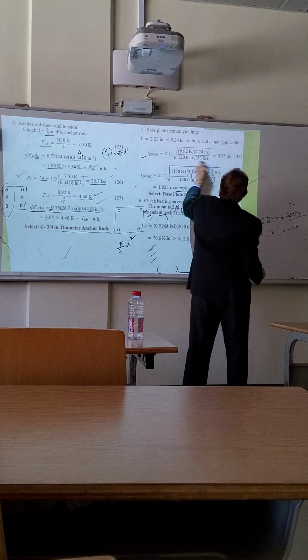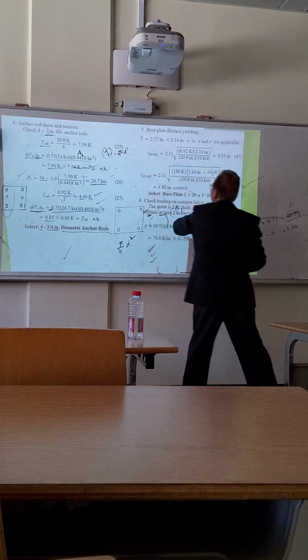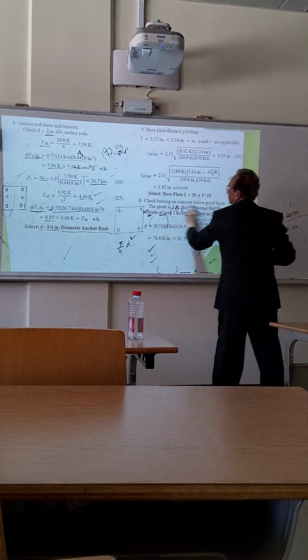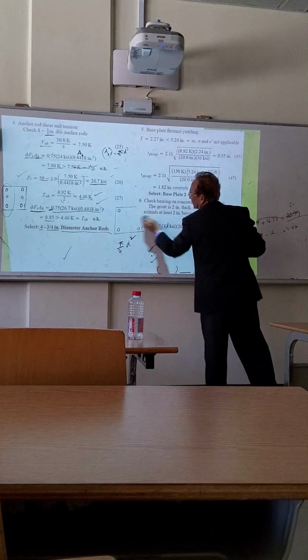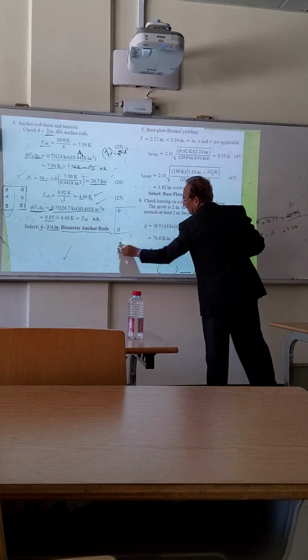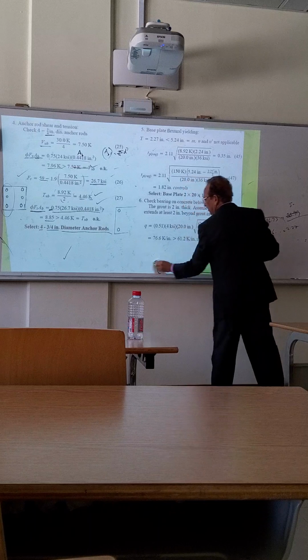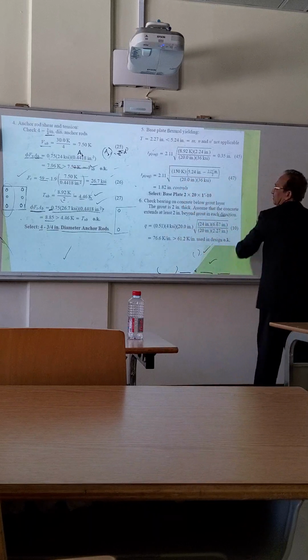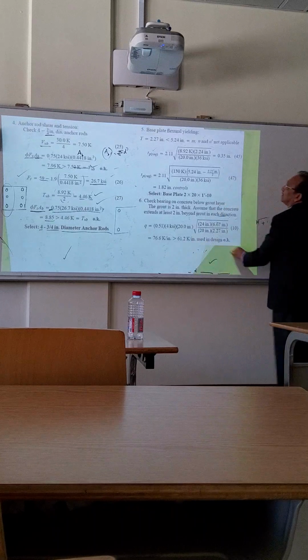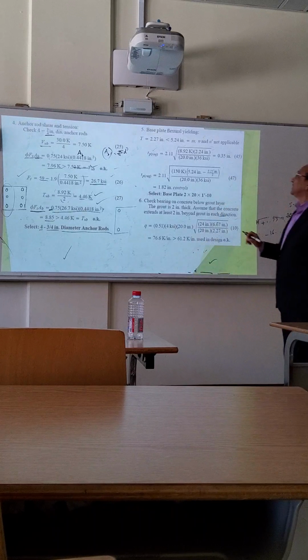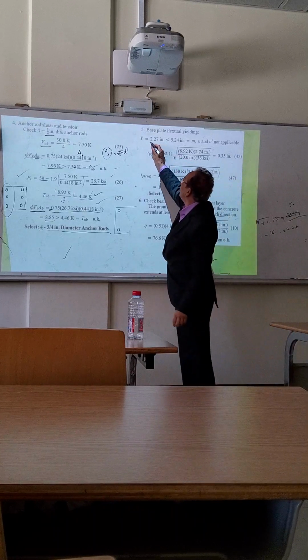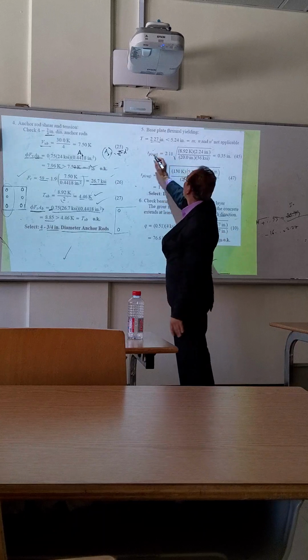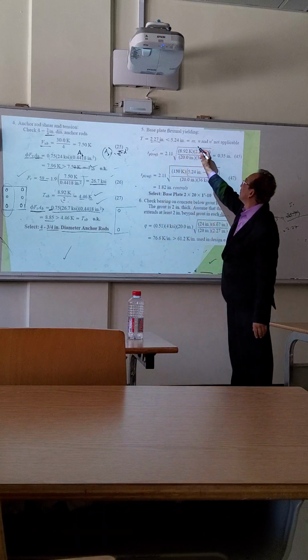Thickness of the base plate. And in this case, we will follow those cases. Which case is applicable? This is case D, right? So in that case D, we look at this one. For base plate flexural yielding, the Y value we have calculated in the previous one is less than 5.24.